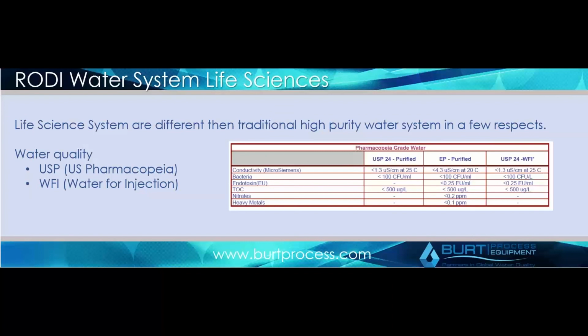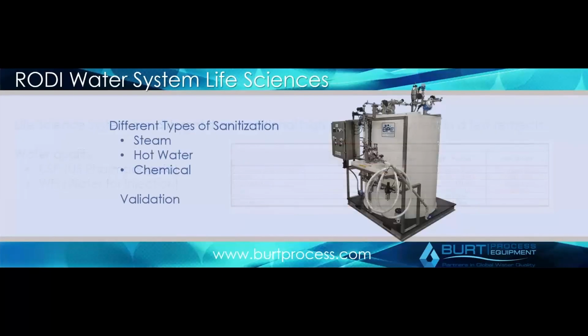But you can see in this case, your primary focus doesn't even get into the resistivity or conductivity range. You're focusing on bacteria and endotoxins and TOCs in those cases. So it's a very different type of water system in that it's focused on very different parameters than most are.